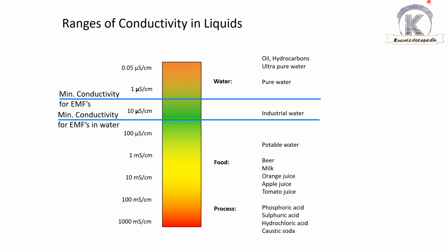So all available liner materials are isolating plastic with a limited operating temperature. This is the limiting factor of the applicability of EMFs. Whilst a magmeter is very tolerant regarding buildup on the measuring tube, there are limitations. A layer on the electrodes will finally lead to a reduced flow signal and the device will stop functioning.